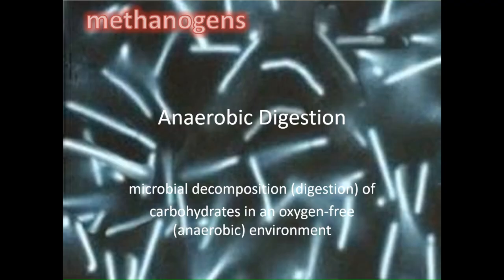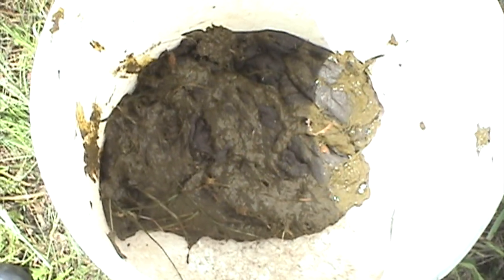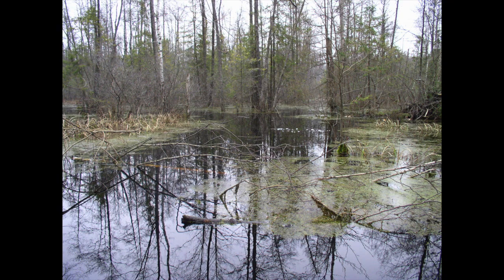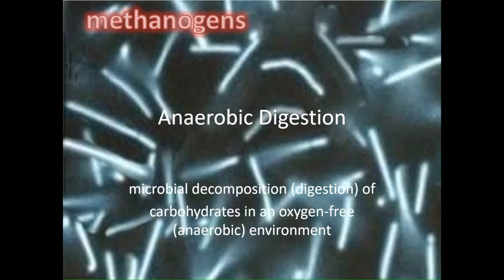These are single-celled, non-bacterial microorganisms from the biological group Archaea. They are required. You can find them abundantly in cow poop, pig poop, and sometimes at the bottom of a swamp, which is where, you guessed it, swamp gas gets its name. You'll need to inoculate your digester with methanogens to make methane. No methanogens, no methane gas.